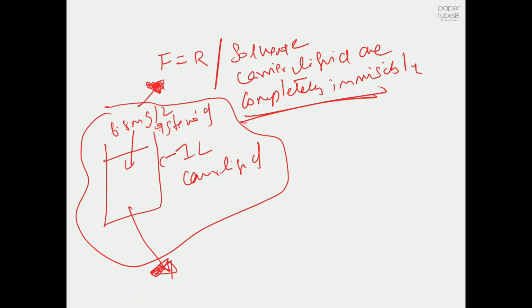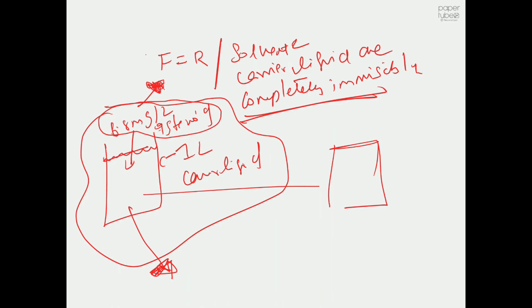So now you understand. If you remove all the 6.8 milligrams per liter from the feed solution using a suitable solvent, whatever the carrier liquid, the volume is going to remain the same, and that will be on your raffinate side. So that's why F is equal to R. I hope you all follow up to this point.